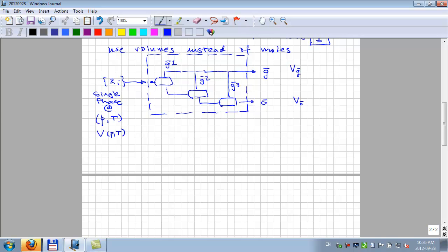We're going to label the phase gas or oil, right? According to what? According to our pressure temperature diagram, which is kind of a pseudo label unless it's right on the saturation, the bubble point. Unless P and T is on that line, the bubble point line, or on the dew point line, we don't really know if it's an oil or a gas. But we're going to use this pressure temperature diagram in a sense to label this single phase as either gas or oil.